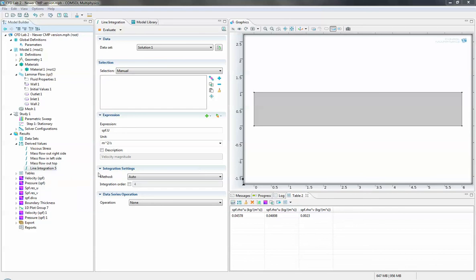Okay, so what we're going to do now is look at this problem and look at a momentum balance. If you think about mass flow, as you saw here, as rho times u, then integrated over a length as opposed to an area, it's really a mass flow rate per meter per second. Well, we're going to have the same issue when we integrate momentum, and it really is an integration of momentum flux. So it's going to be rho u times u normally.